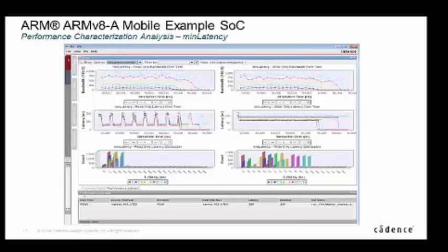And obviously the QoS system that you employ is about allocating priorities to the masters, that can be dynamic. So you can say maybe the display, and obviously one of the masters up on the far right would be modeling the display, you could say I want a QoS level of this, but it's got scope to bump up the priority if it's not received a certain amount of data by a certain amount of time.